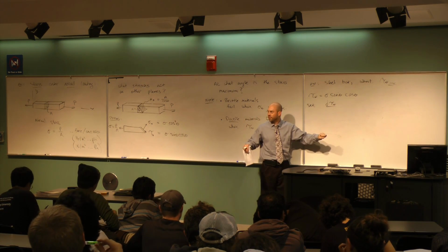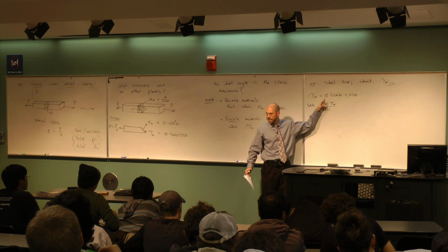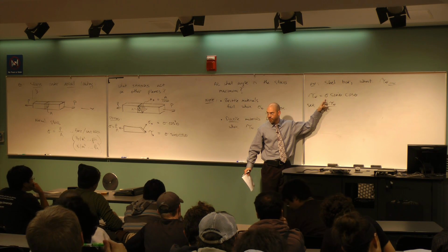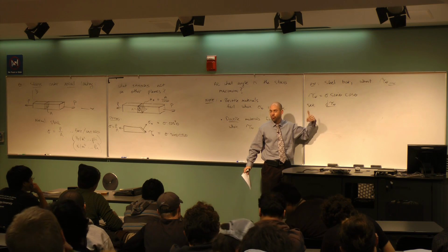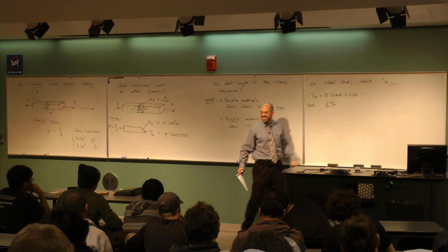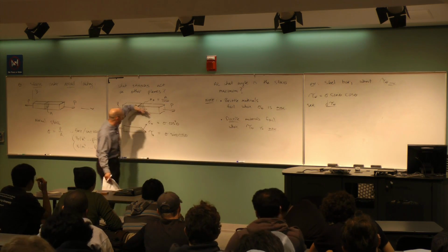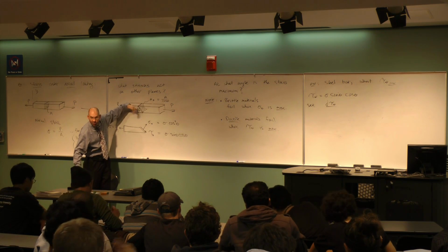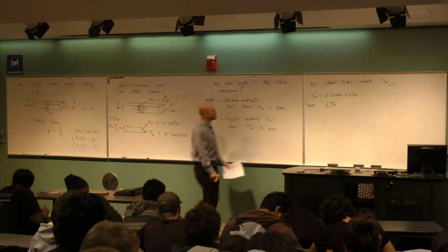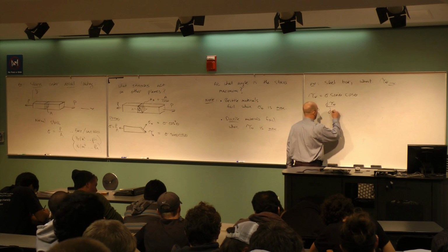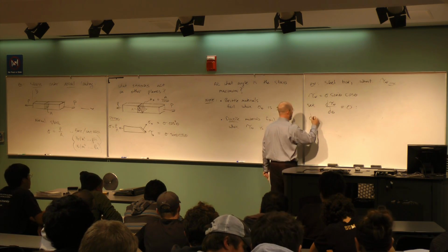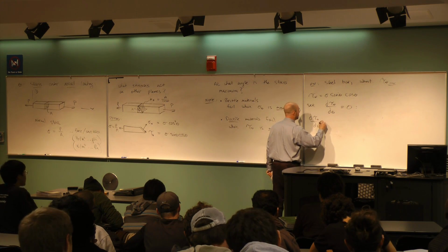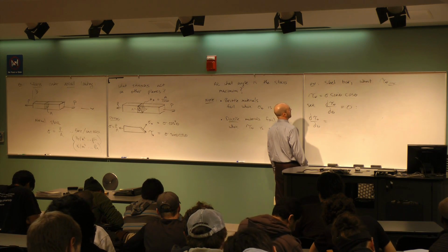So I know what my bar is. I know what my force is. Is the sigma a variable here? It's a constant, right? It's a parameter. So I'm taking the derivative with respect to what? It's the angle, right? I'm trying to figure out at what angle does this occur. Equal to 0. Okay, so let's do that. Derivative of tau theta with respect to theta is what?